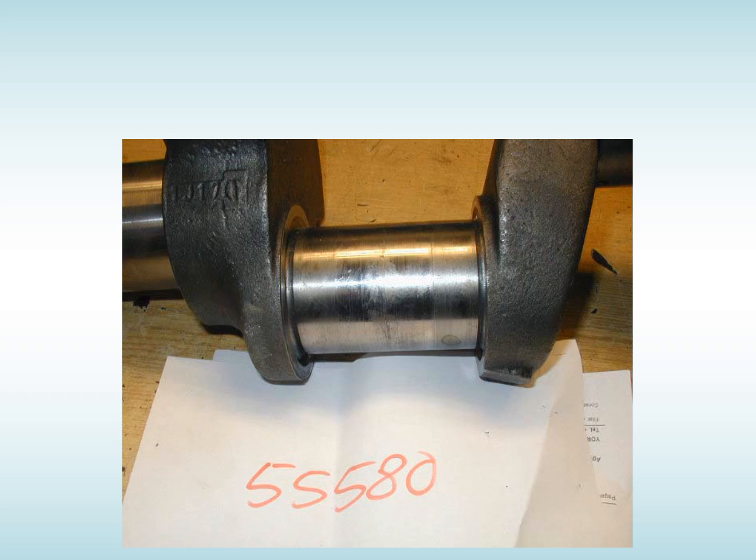Generally speaking, you can get those reground if they're badly damaged, but there's not that many places now doing that, and it can also be very expensive. So you'd have it reground undersize, and you'd have oversized bearings to make up for it. Generally, 10 to 20 thou, you can have them ground.